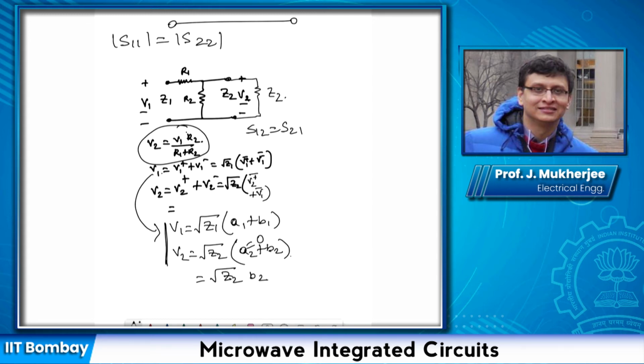And so now I have already given you the hint, this equation which relates V2 and V1. Using these two equations we can have a relation relating A1, B1 and B2, and that way we can obtain a relationship between S12 and S11. Also note that the input gamma in, when A2 is equal to 0, and when is A2 equal to 0?